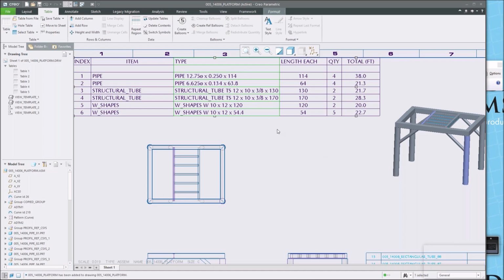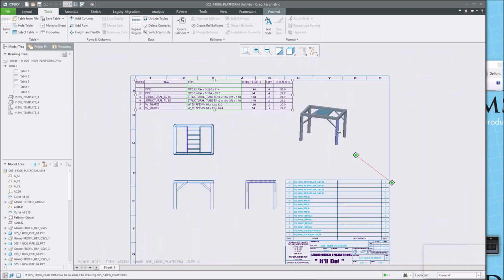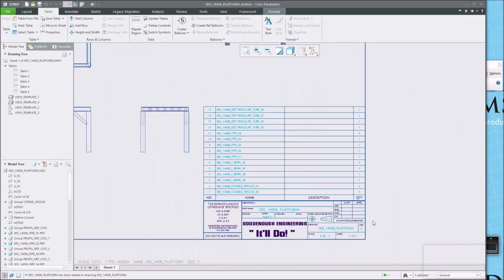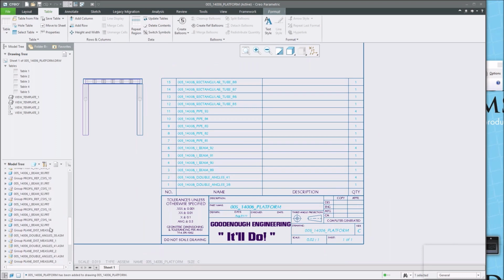All right. And then from there, we also have the BOM down here in the bottom right. And this BOM is now a part number based BOM. So remember I mentioned the different part numbers that we have, where we have the 92 and there were multiple versions of 92. If we come over here and find 92, we can see there's a quantity of 4. 91, although it's the same one, is simply at a quantity of 1. So now we can go in and start to reuse things.